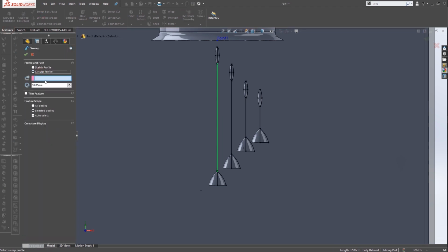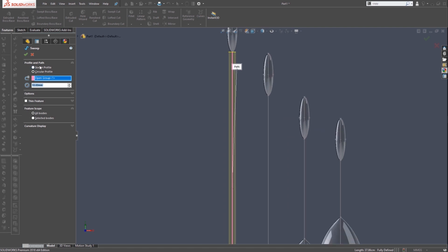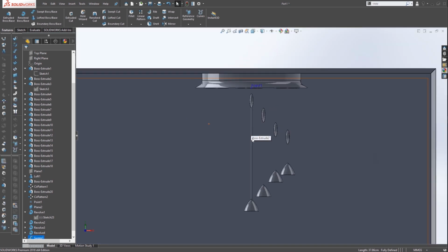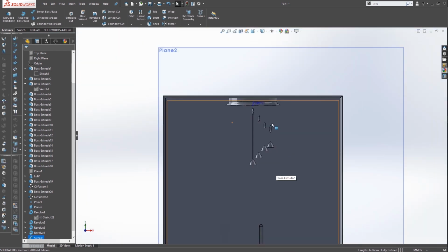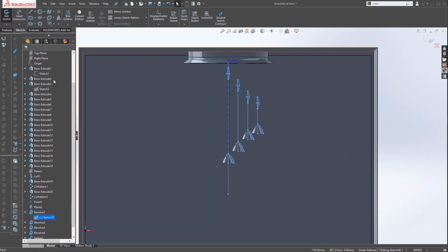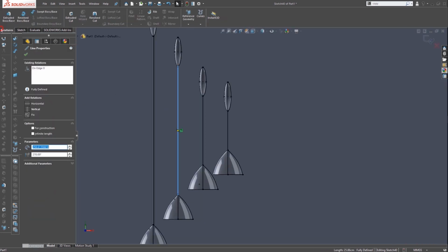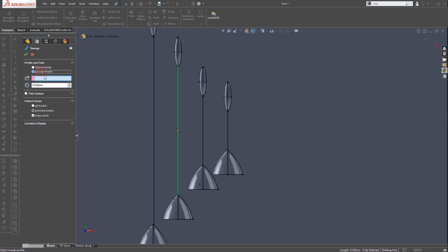Go for circular profile. I want to select all bodies and select a lesser value. I will choose 5 mm and it's fine. It's done. Now I'm gonna do the same for everyone. Just control it, press OK, convert entities, select it, go to swept, circular 5.